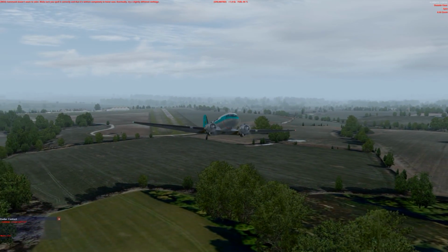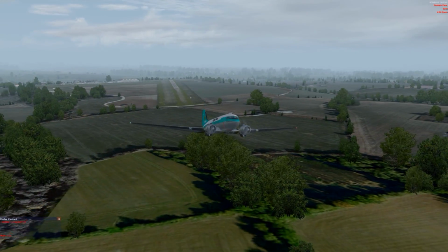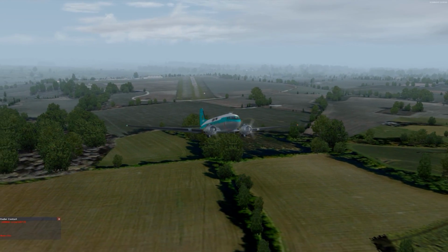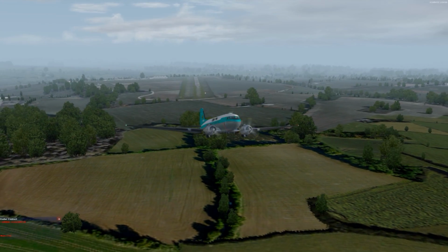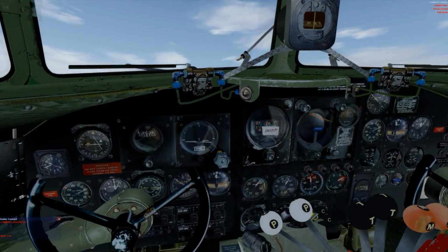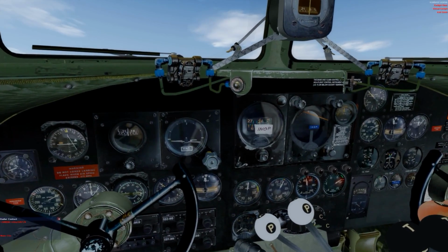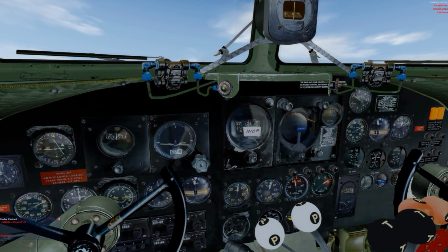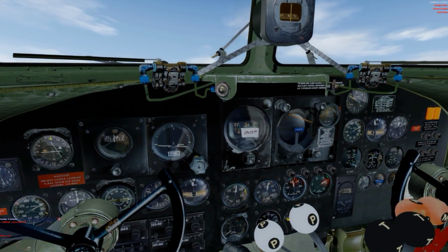Cowl flaps armed. Air ignition switches off unless weather. Max permitted limits for max continuous after takeoff: 2500 RPM, 41 inch manifold pressure, oil temp 100 Celsius, cylinder head 245 C. Ready for after takeoff checklist. Squawk 5102, expect Manchester 124.2.